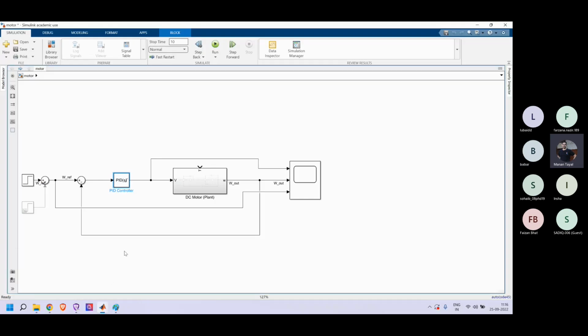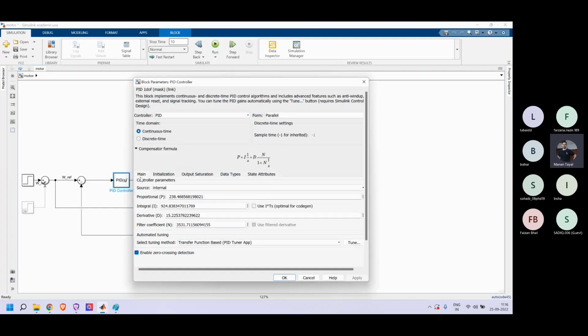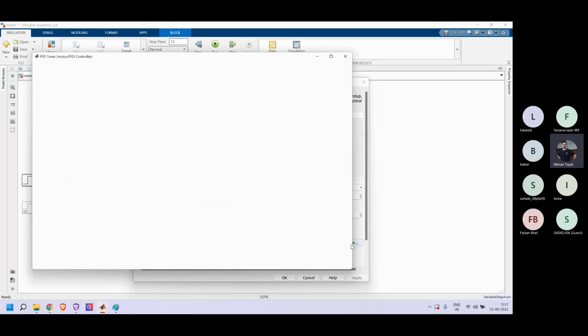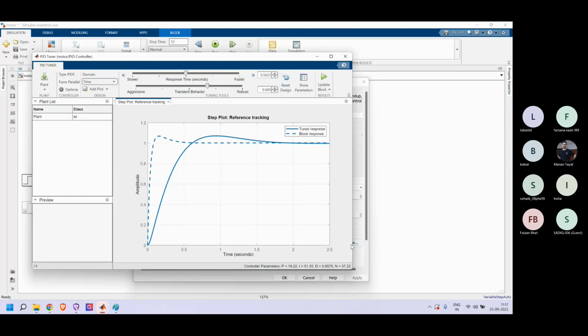So also if we tune my parameters, I had put my control parameters in a very idealistic way, right? I want my response to be very quick as well as have less overshoot, right? So probably I'll tune these parameters again with my output saturation and see how my response changes now. So how an ideal response now looks.